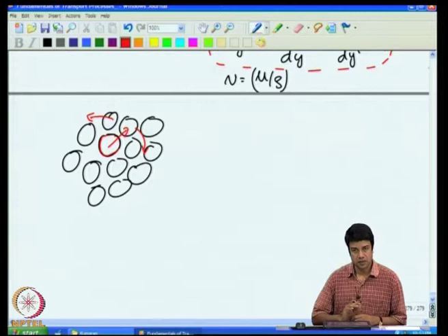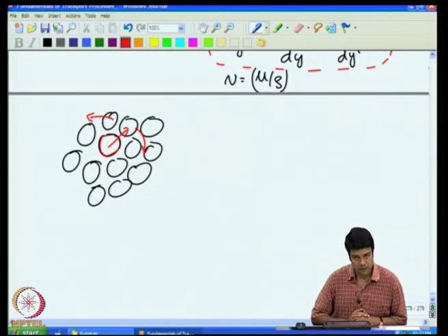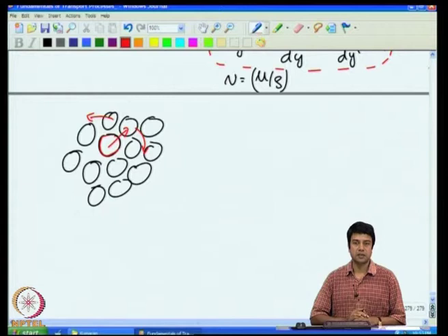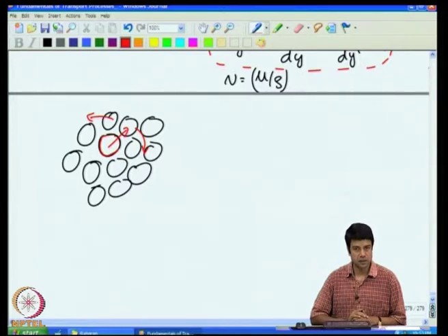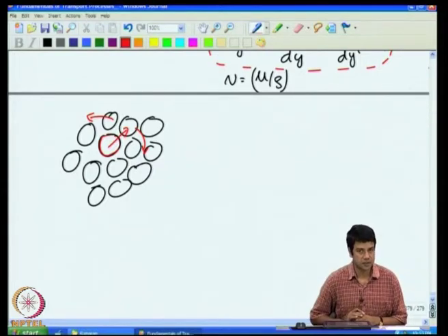Because of that, the transport is a very fast process, and due to that, the Prandtl number is actually very small in liquid metals, whereas in non-conducting liquids, the transport takes place due to the physical rotation or vibrational motion of the molecules, and there it is a relatively slow process. So, on this basis, we had rationalized why the diffusion coefficients have the values that they have in liquids and in gases.